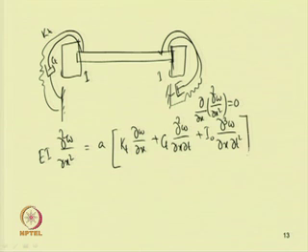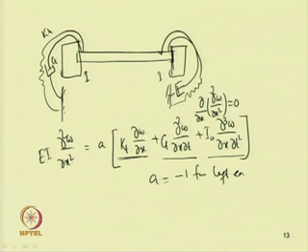It may be noted that this del W by del x is the slope, that is theta. So, one can have this equal to I0 into del square theta by del t square, that is the inertia due to this torsional mass, then this is due to damping and this is due to stiffness. Here A will be equal to -1 for left end and +1 for right end.